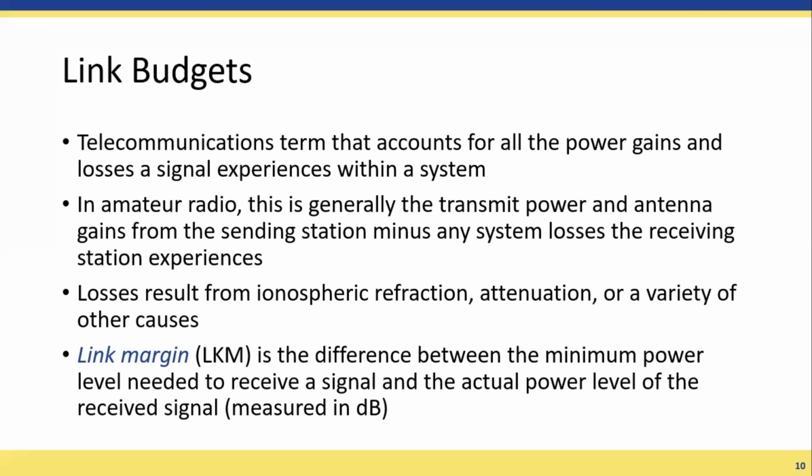So if I'm trying to talk to Jason in Texas from Huntsville, and I'm running 30 watts and he can just barely hear me, we'll say we've got a link margin of about 0. That's perfect. I crank up my amplifier, and he goes, wow, I can hear you this much better, 10 dB better, then I've got a link margin of 10 dB. So it's how much margin do I have before he can't hear me anymore, right? How much power up? So that's your link margin.